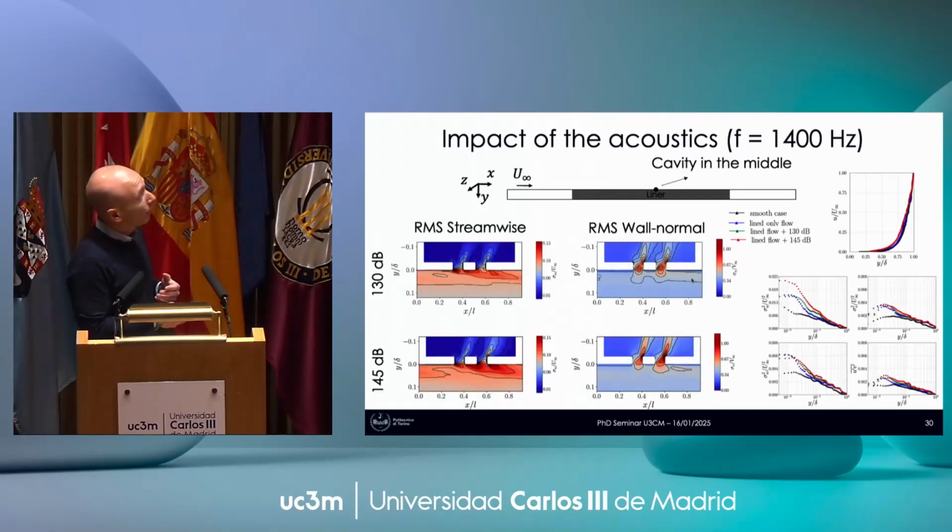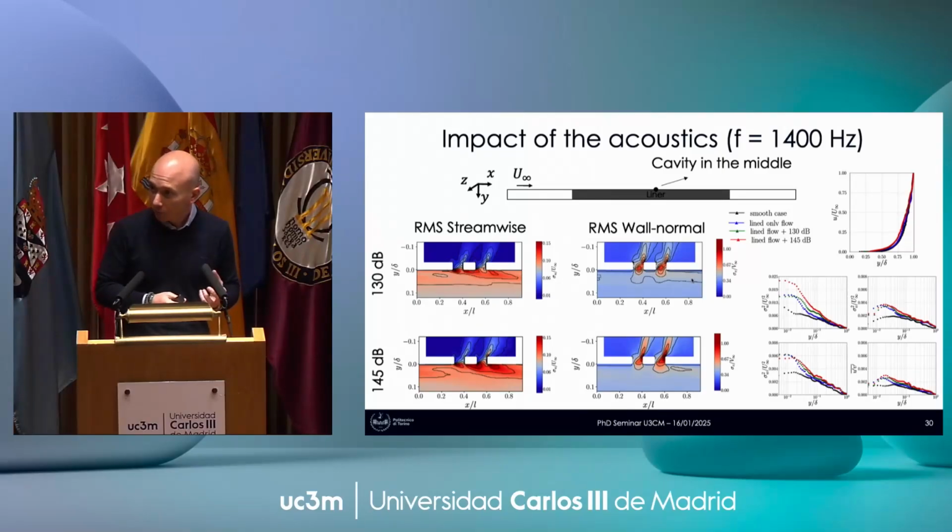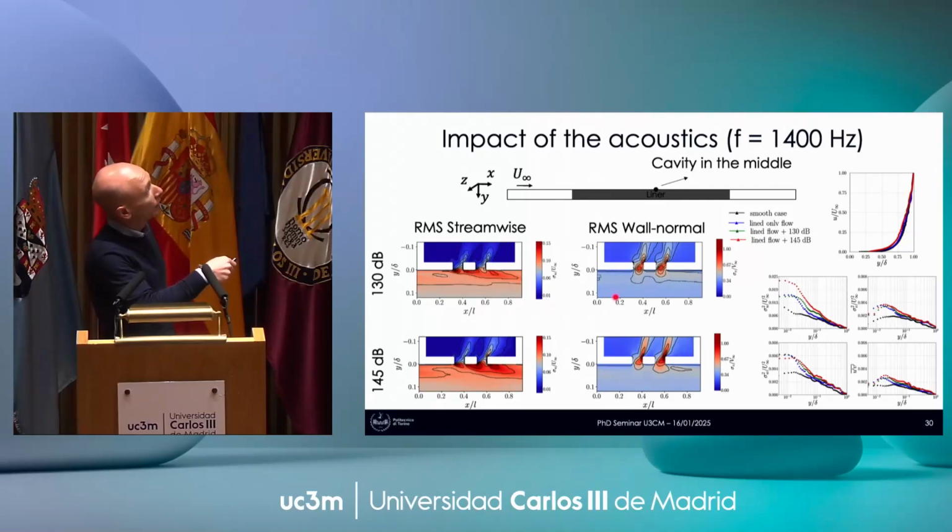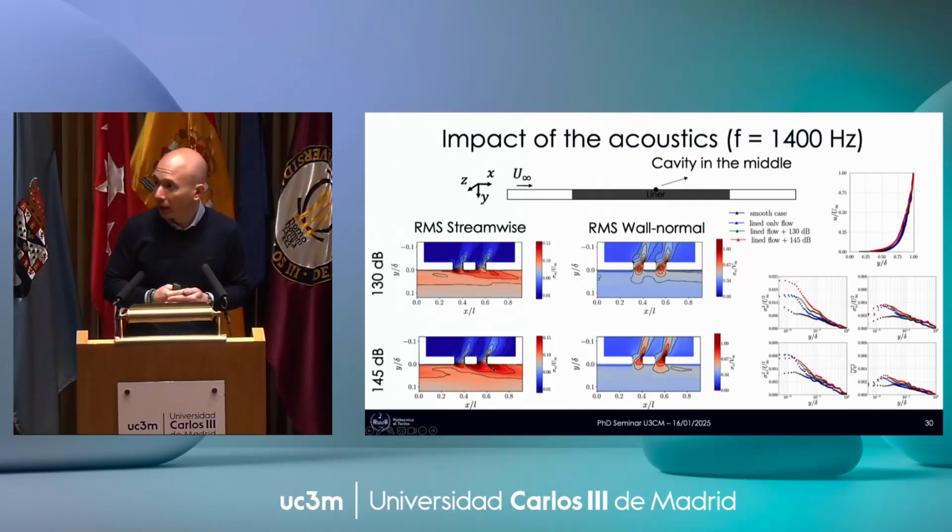Therefore, the amplitude of the velocity fluctuations is also changing. So why did we see that trend in delta star? Because I'm continuously pushing momentum with different frequencies and different amplitudes. There is a connection between the two orifices or the three orifices, depending on the plane where I am, and this is causing the flow to move up and down.